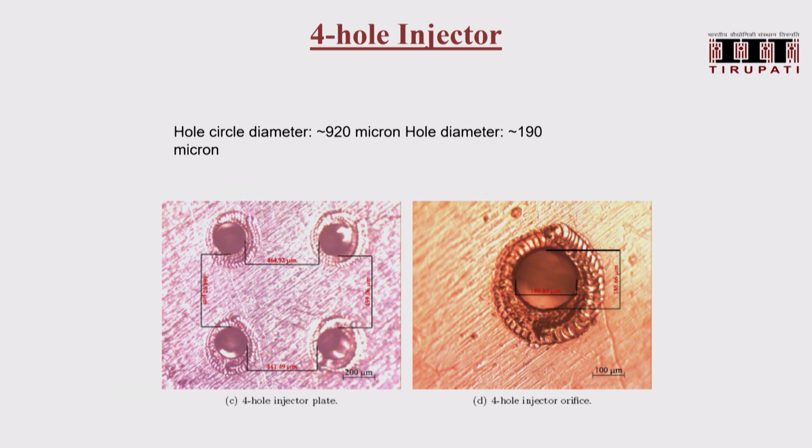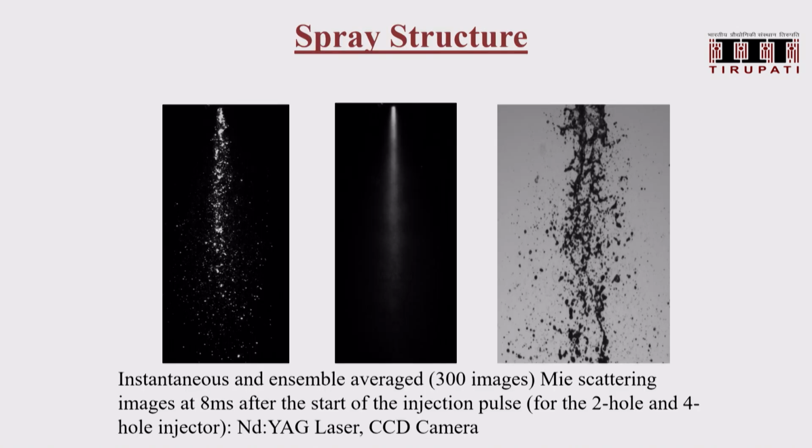Once we measure this, then we need to see how the spray looks like. Whether you have a series of drops or still a liquid, because by the time this interacts with the air, you want as many spherical drops as possible, right? Again, a sphere gives you a large surface area to volume ratio. So this is the simple spray structure.